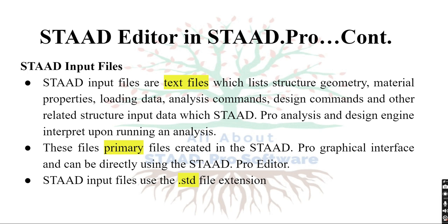Actually, we are doing the analysis and design part of a structure or a building in the software, and all the commands we are giving to the STAAD Pro software will be fed automatically into the STAAD input file, that is, the STAAD editor file. Every input data is fed in the STAAD editor.